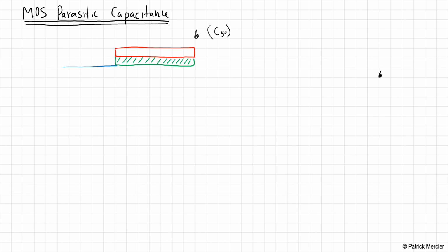And then underneath all of this, we have our silicon substrate. And within this substrate, we have some doped regions that create the source and the drain. Now, just to label, this is the gate, this is the source, this is the drain, and this is the P substrate.